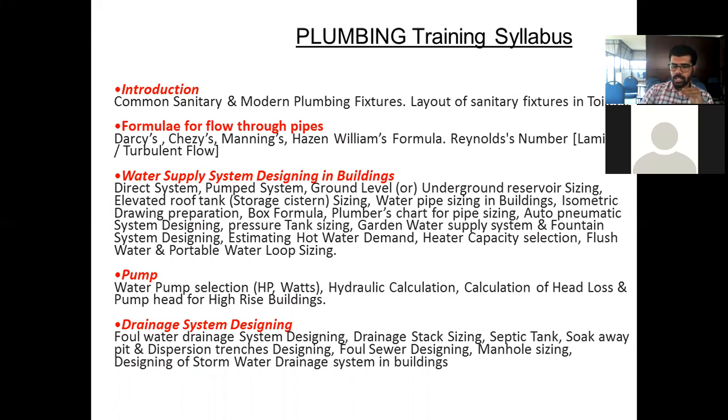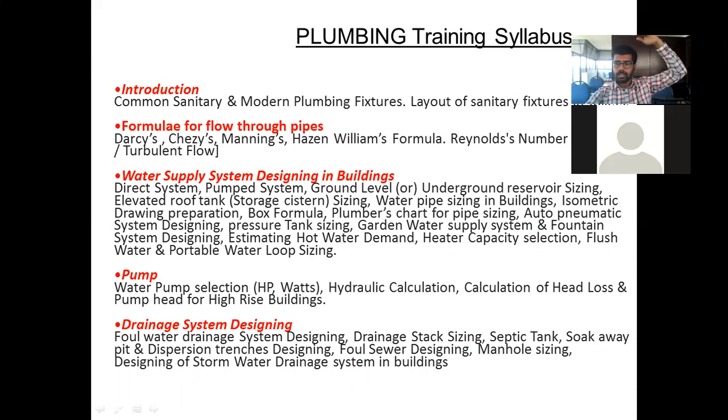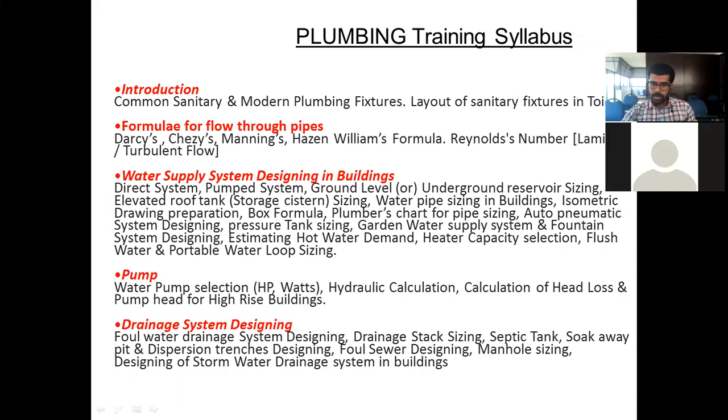And when we are dealing with this, you may ask what is the purpose of studying all these things. When we are trying to give water supply to these, we should be able to know at what height the water supply should be given. So for a water faucet, you have to give this much height from the floor. For a wash basin, for the pipe connection or the wall connection, from the finished floor level, you have to give this much height. When you are dealing with showers, there is a height. Depending upon that, for the water closet, that area, the height should be this much. There are proper dimensions and proper heights, so we have to know about that.